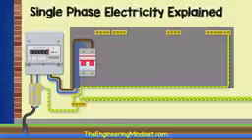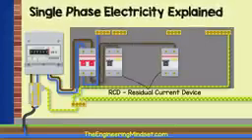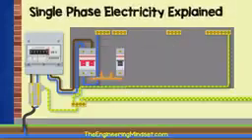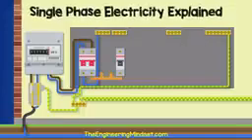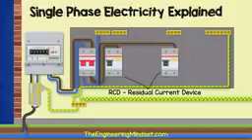At the bottom we find the neutral wire, which will connect to the neutral block connection. We might find one or more phase wires coming out of the bottom of the main switch to feed the RCDs. If there aren't RCDs being used, then a bus bar will feed the circuit breakers, but we'll look at that again shortly. The phase line enters the RCD or residual current device, again usually entering via the top.